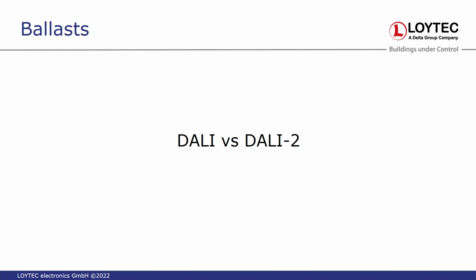Probably someone says, okay, this is a DALI ballast, or a DALI LED driver, so it will not work with a DALI 2 gateway like LDALI, for example. So this should be our conclusion in order to make the customers understand that this is a DALI 2 driver, but in the end, it's the same as a DALI driver.